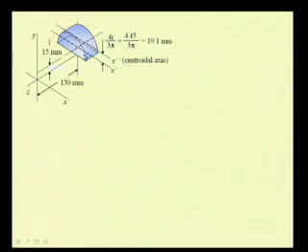Let us take this semi cylindrical feature. The centroidal axis is x double prime, and this axis, that is x prime, is an axis which is parallel to this centroidal axis, but it is lying on the base of this semi cylindrical feature, or I can say the diametrical plane of this cylindrical feature, and we have the axis x about which we are interested to find the second moment.